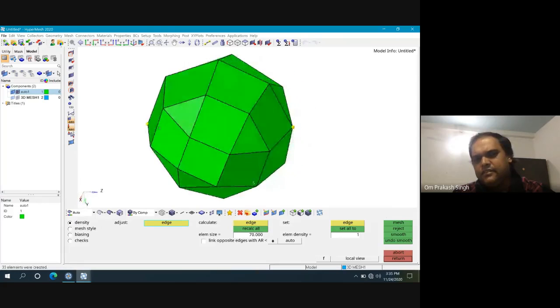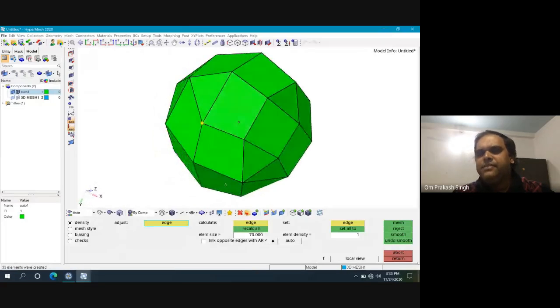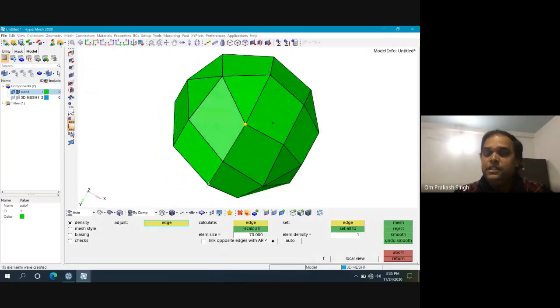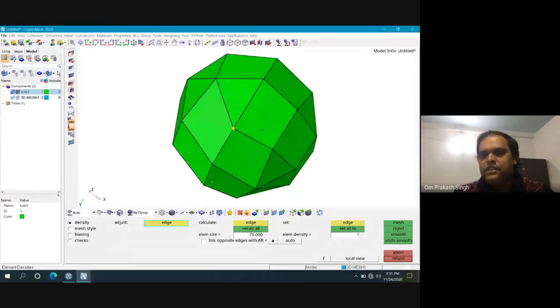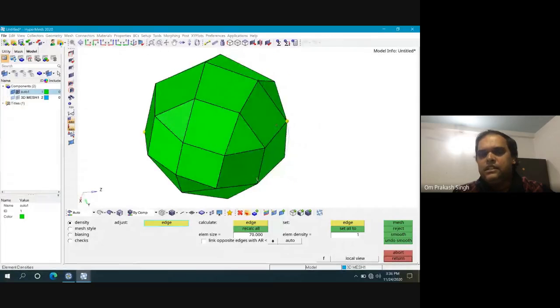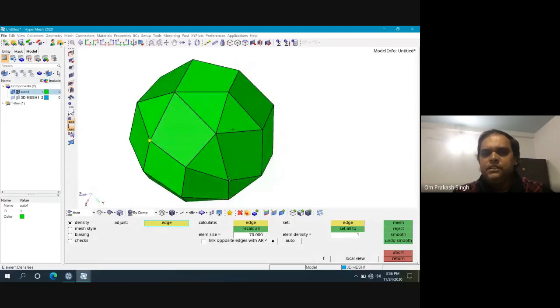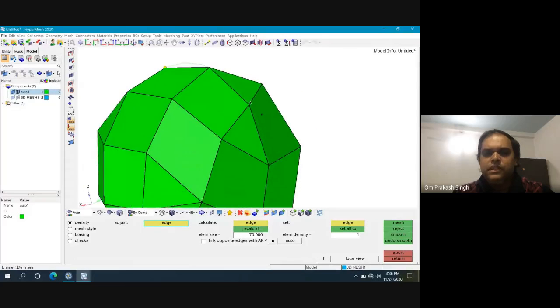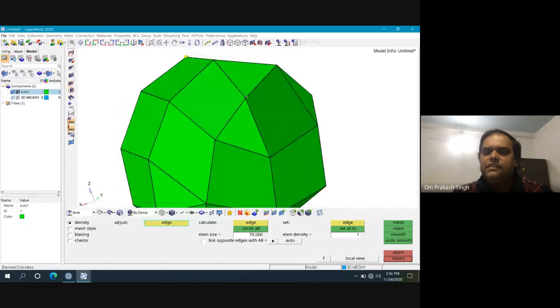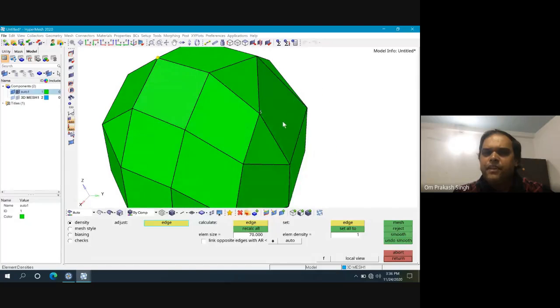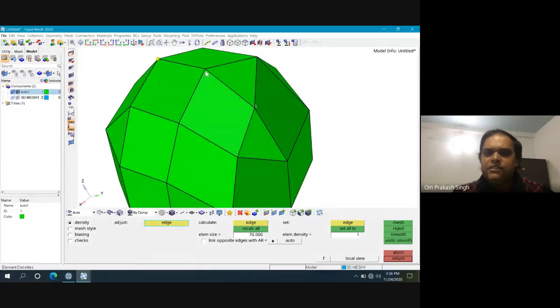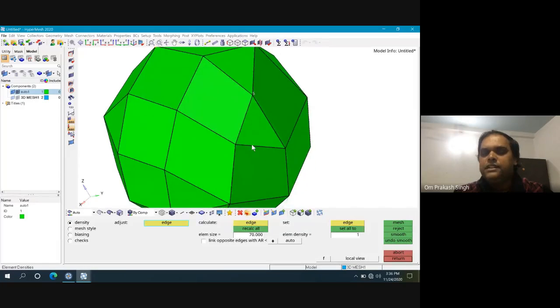Now you see, the purpose of meshing, first of all, is to capture the geometry. By no means is it looking like a sphere. It resembles that, but it's not capturing the geometry. These surfaces are flat, and you can see these elements are highly stressed. I'll cover tomorrow how to check the element quality and what precautions one should take while creating a proper mesh.